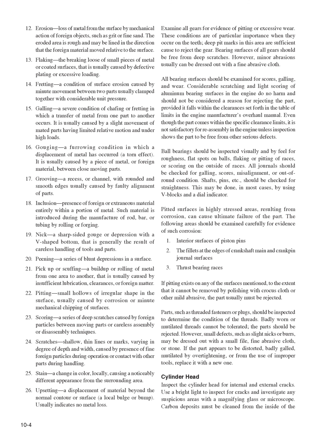Parts, such as threaded fasteners or plugs, should be inspected to determine the condition of the threads. Badly worn or mutilated threads cannot be tolerated; the parts should be rejected. However, small defects, such as slight nicks or burrs, may be dressed out with a small file, fine abrasive cloth, or stone. If the part appears to be distorted, badly galled, mutilated by over-tightening, or from the use of improper tools, replace it with a new one.